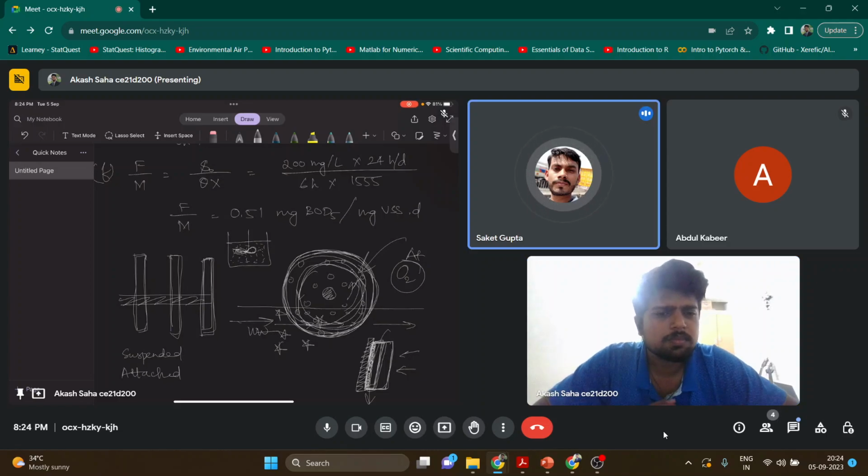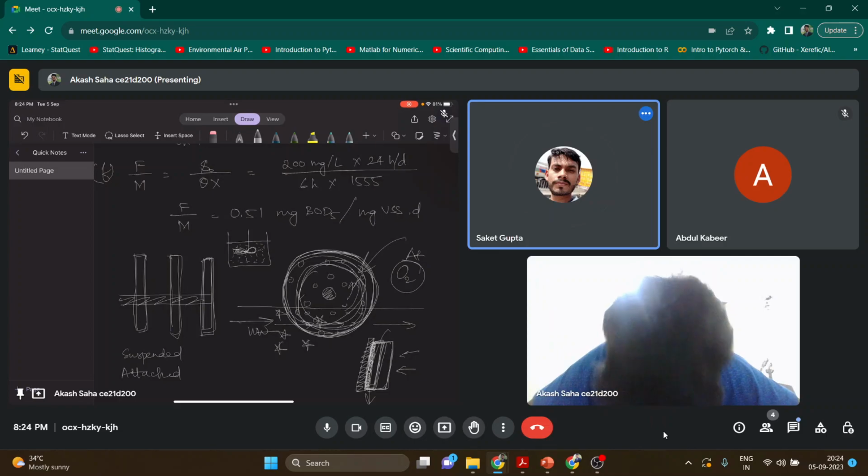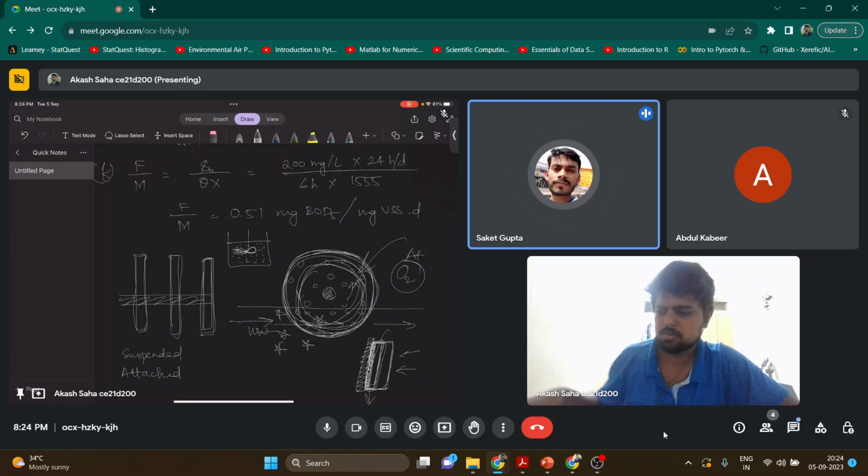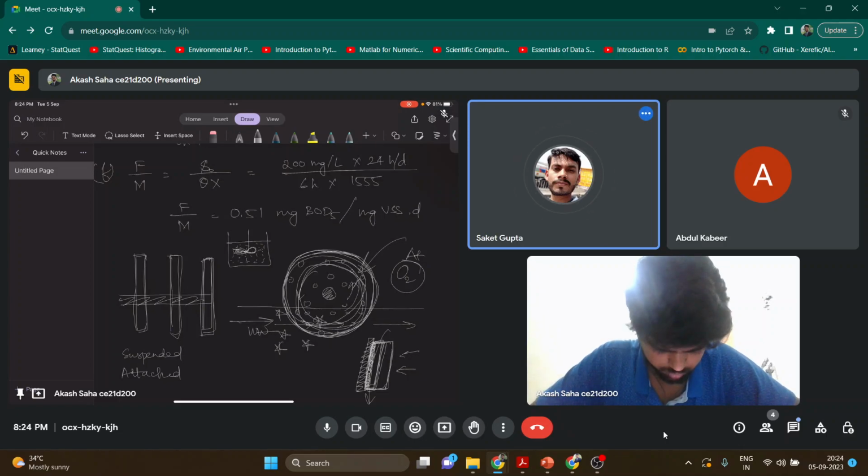Sir, in design criteria, if our theta c value comes out between 10 and 25 and our HRT value is less than 12 or more than 24, so it means our calculation is not correct.